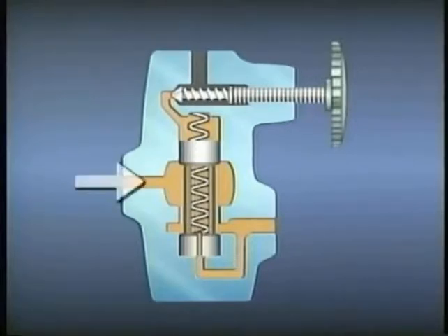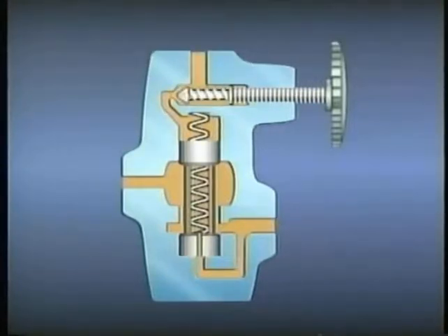However, if the inlet pressure is greater than the desired outlet pressure, then the pilot valve and spool come into play. Since fluid pressure is sensed at the pilot valve disc through the hollow spool, the higher inlet pressure at the disc overcomes the force of the spring. The spring contracts and flow is diverted to the drain passage.